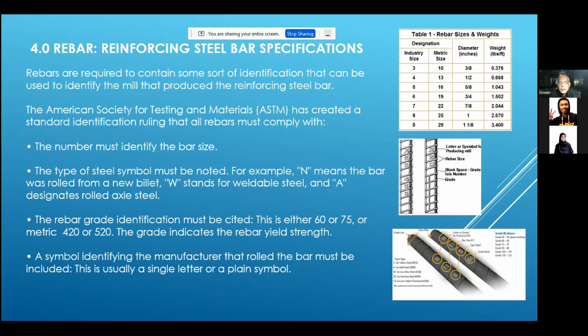When the material is delivered to site, it comes in big lorries, and they unload it at the site. Before that, the contractor has to supply the delivery order. Make sure the order is the same as we expect, as delivered, and then the engineer will check all the documents and the labeling, so that the steel delivered to the site is according to the specification specified by the engineer for such a system.